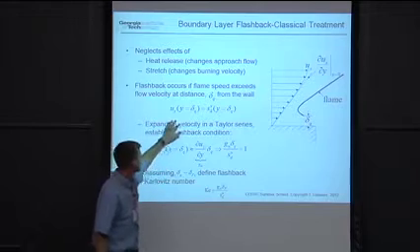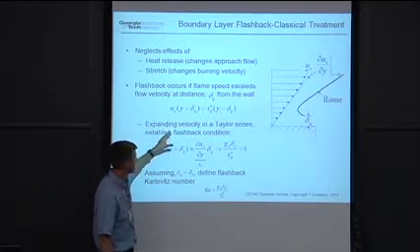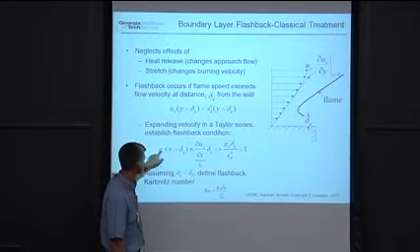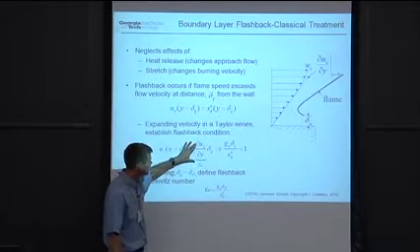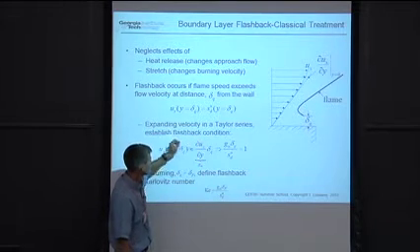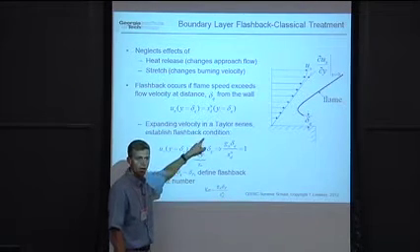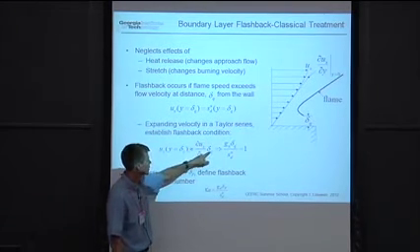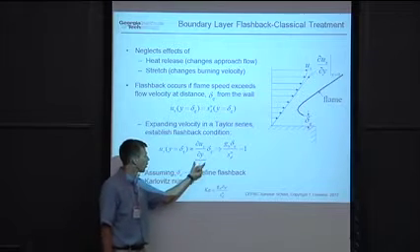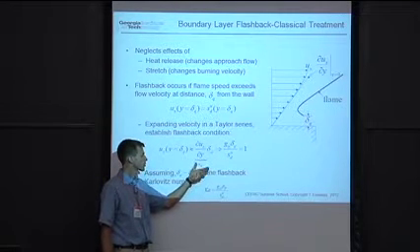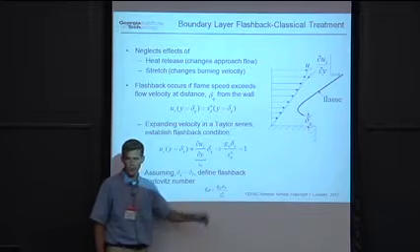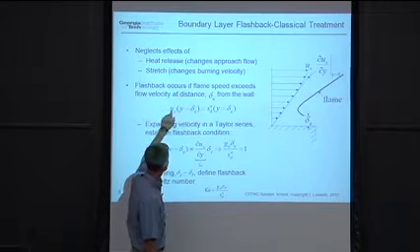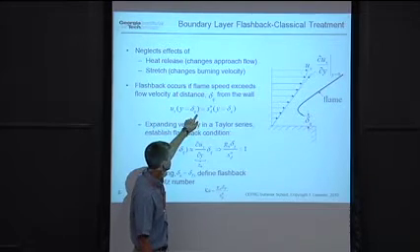Okay, so when the flame speed at del Q is equal to the velocity, that's your critical flashback condition. So if you take the velocity and expand it in a Taylor series about the wall condition, the axial velocity at the quenching location, u_x at y equals del q, is approximately equal to, well, the velocity is 0 at the wall, so the zeroth order term is 0. The next term is the gradient, du_x/dy times del q. This is often called the velocity gradient. I'm going to call it g_u. So I'm going to replace this velocity by g_u times del q.